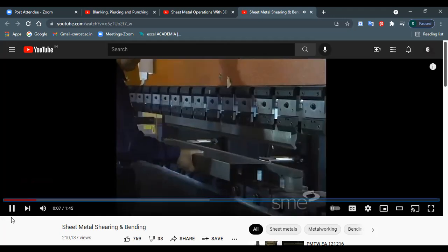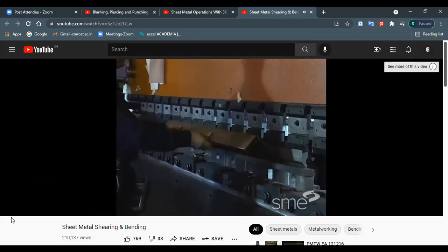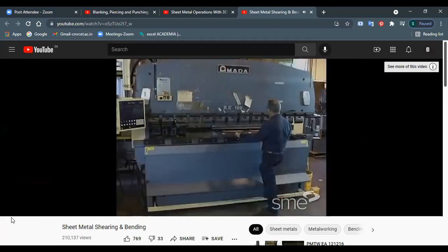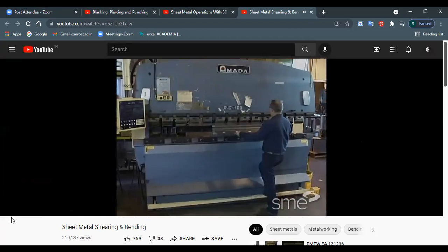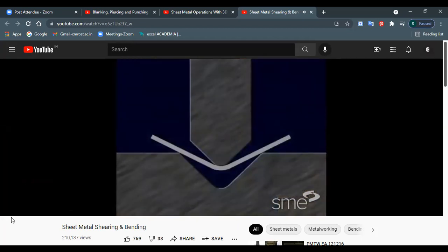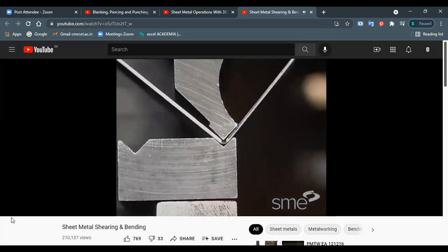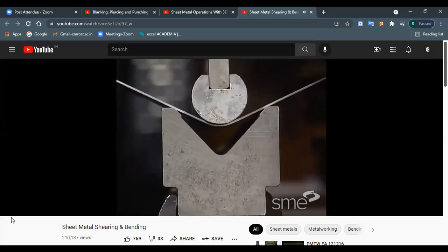In a typical press brake bending operation, a piece of metal is placed between the upper and lower dies and formed by means of the force and pressure exerted by lowering the ram. On some press brakes, the ram and upper dies remain stationary, while the bed holding the lower dies provides the force that bends the part. Three contact points are involved in a bend: the tip of the punch and two points on the female die. The material is bent to the desired angle as the punch enters the die. The larger the die opening, the smaller the force required to form a given angle.